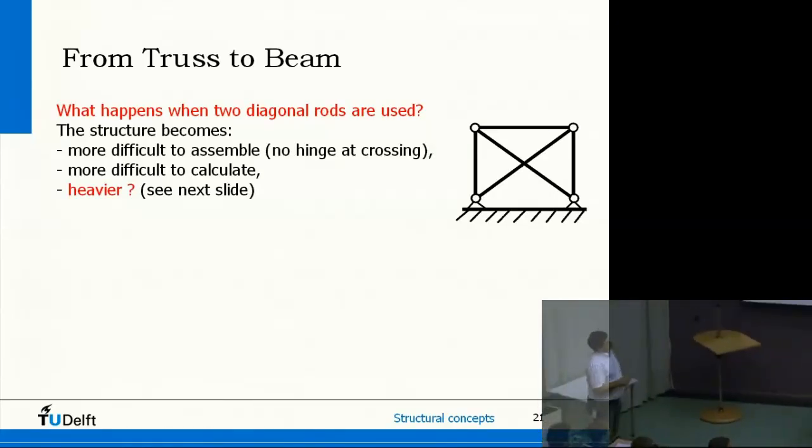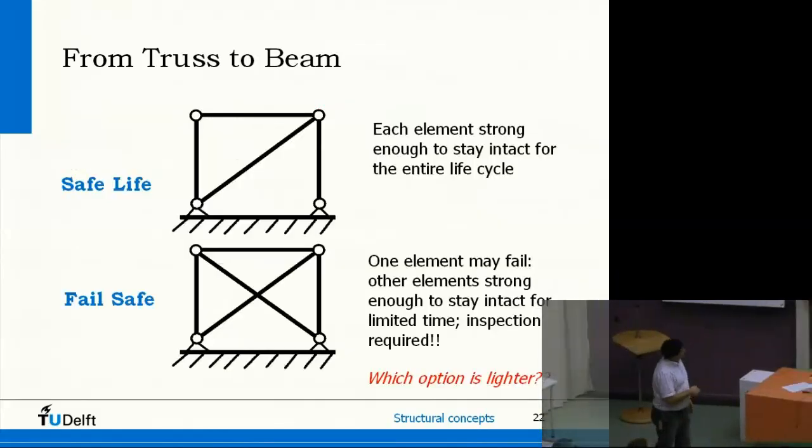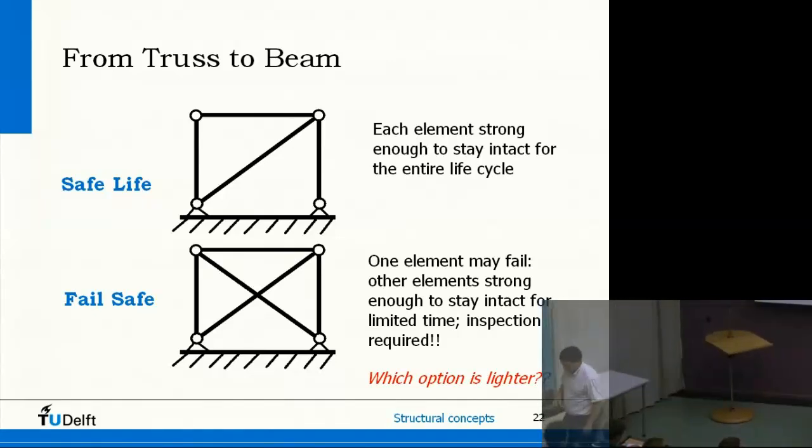So it is more difficult to assemble. It's more difficult to calculate. Is it heavier? Well, in the first instance you would say yes. It has some reserve, and that's my advantage. It is a fail-safe structure. Now I will try to explain two concepts that you see in structures, safe life and fail-safe.